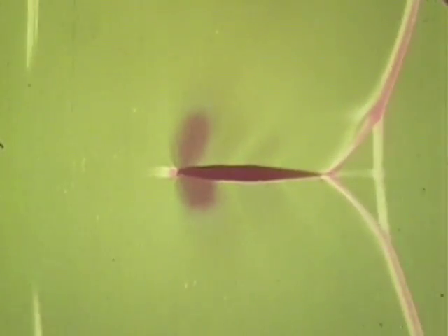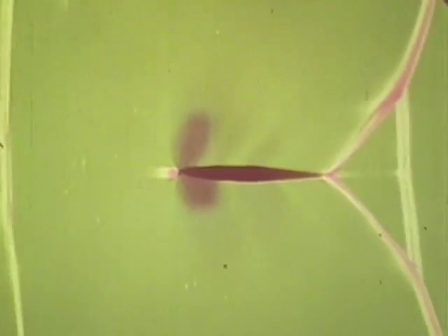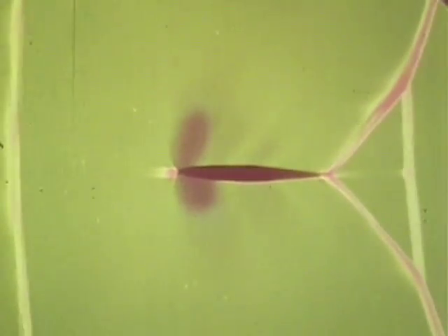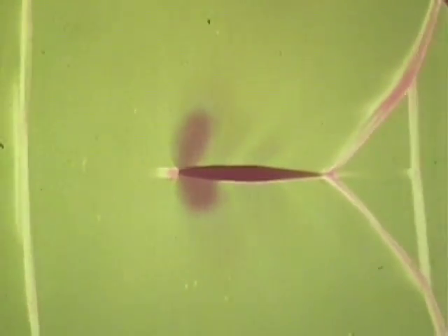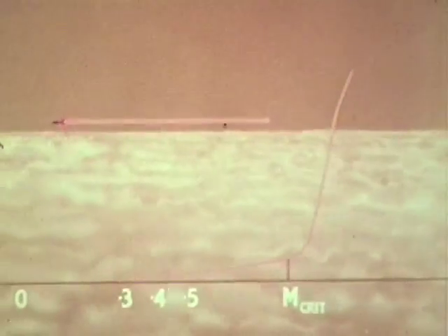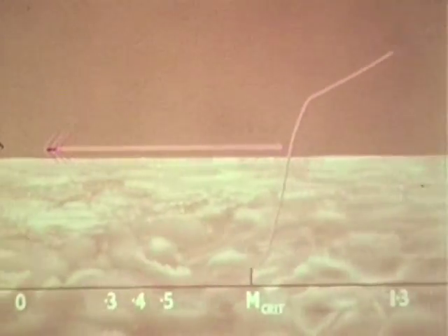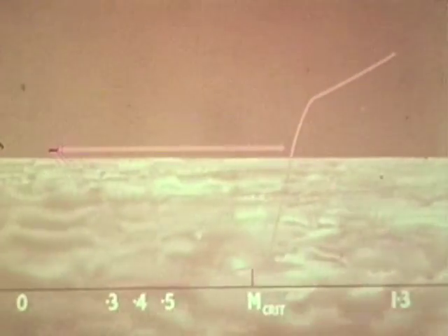Above Mach 1, the wing shocks have reached the trailing edge and now grow much more slowly. The wave drag of the bow wave also changes, but gradually. So the drag rise becomes less steep again towards the upper end of the transonic range.